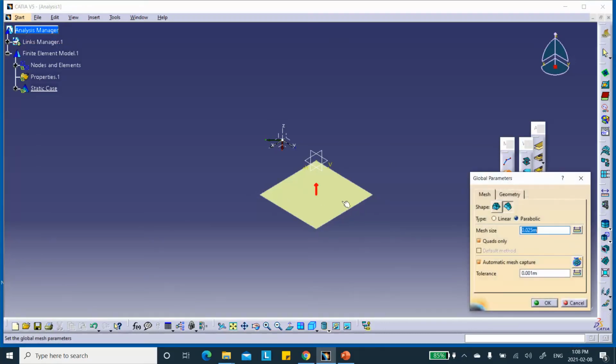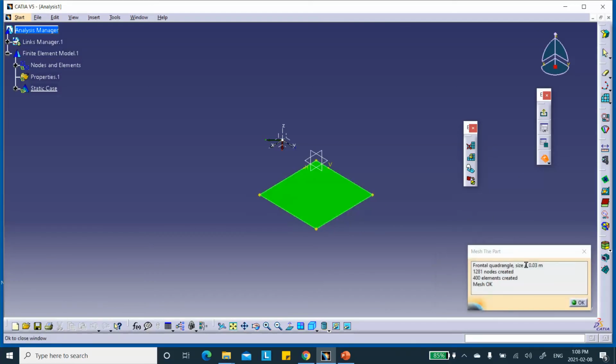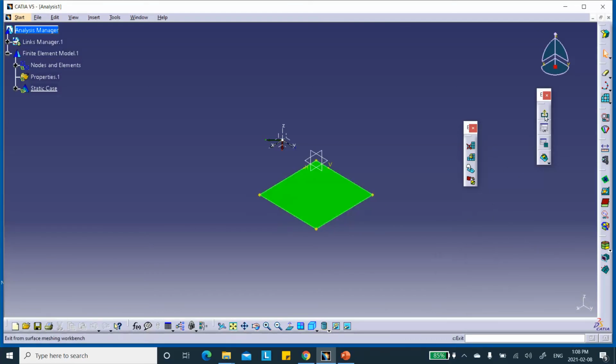This is the mesh. Okay, the size I'm going to make. Let me see now. Yeah, I had 50 or half a meter on each side, and I want to put 20 elements there. It just happens that this is correct because I already used it. So that's going to be 20 elements this way, 20 elements that way, and quadratic, parabolic, fine, and then mesh it, and then OK, and exit.